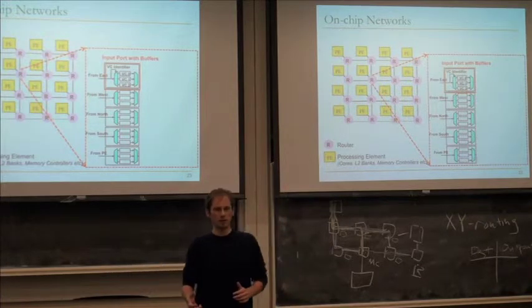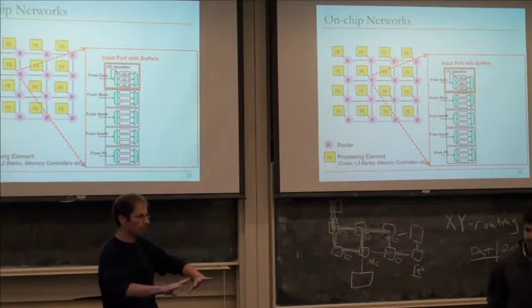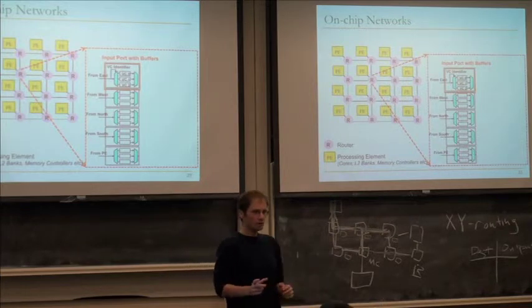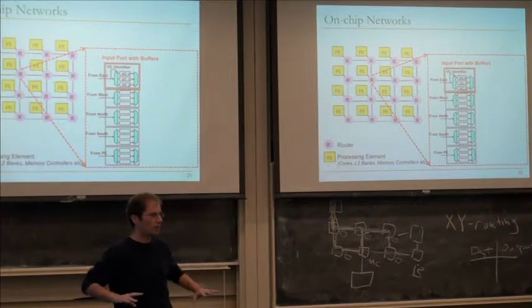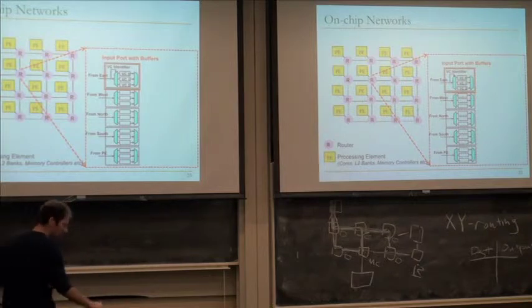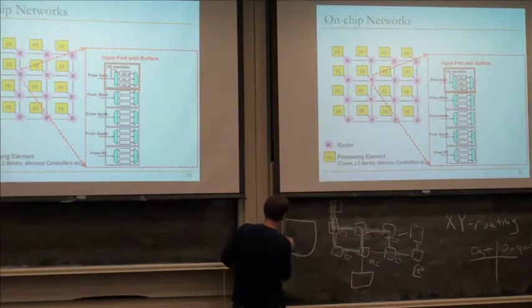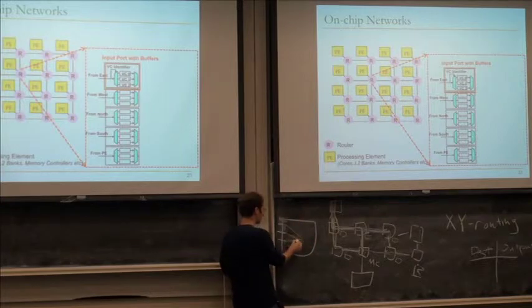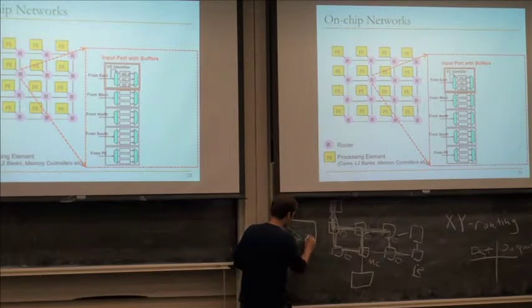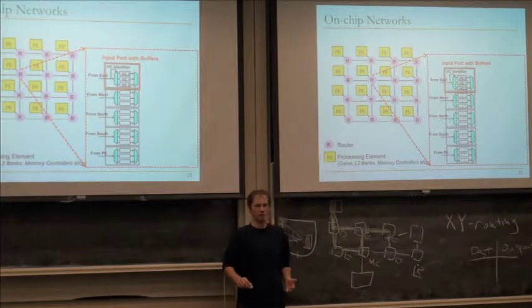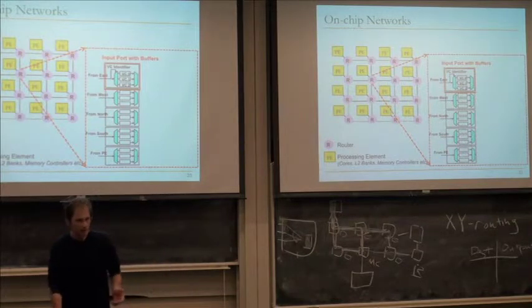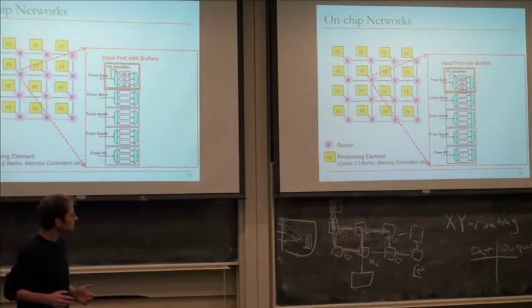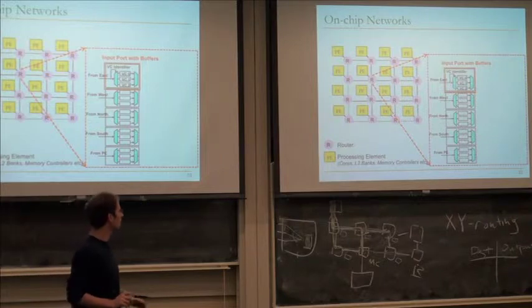But if you do something like output buffering, in the worst case, all of the flits that come into a router in one cycle might head toward the same router output. So if you don't have any capacity for buffering until the router output, you need to handle the case where all 5 flits, or say n flits for an n input router, can come in the same cycle. We have n inputs, and we need to handle the case where all of these go toward a single output. So we need redundant data paths to handle this. And then we need some large wide FIFO that can write n flits into it in the same cycle, so we need a lot of write ports in the same FIFO. That's the reason we do input buffering: we have this guarantee that on a given input, we'll only get 1 flit per cycle. So essentially all recent router designs are designed this way.